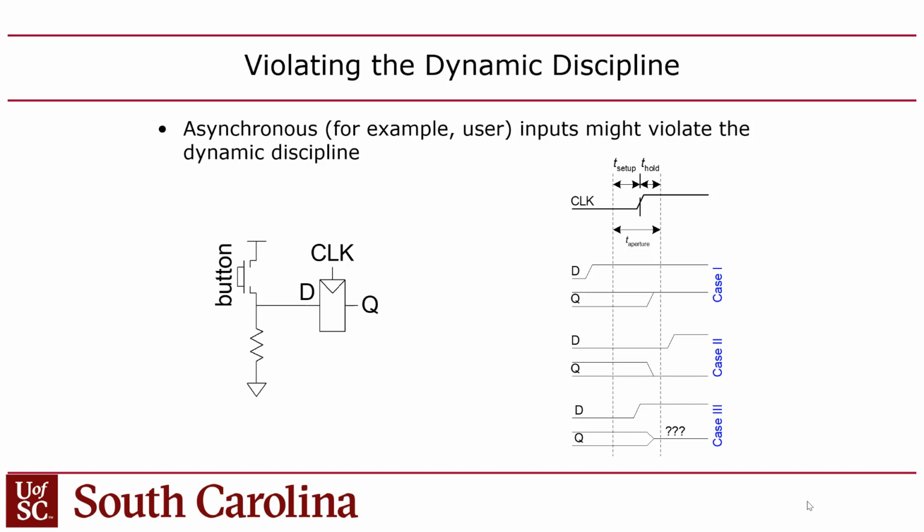Now you might say, well, you have to flip it, what's the likelihood of that? It's actually a little higher than you might expect. Yes, there's a debouncer, but even with the debouncer, it's non-deterministic. The CAD tool has no control over when the user flips that switch, and if that switch is connected to a flip-flop, there's no guarantee that you won't put that flip-flop into metastable mode, into metastability.